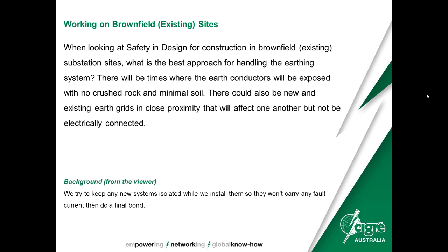Now, in terms of construction safety, when you bond the grid in and how you maintain separation or combination, that's not the only safety consideration. There's a lot of other things about safe working around them, about power supply to your ATCO huts and to equipment, and those things, in our way of operating, tend to work their way into a site safety plan for the earthing system on brownfield sites.